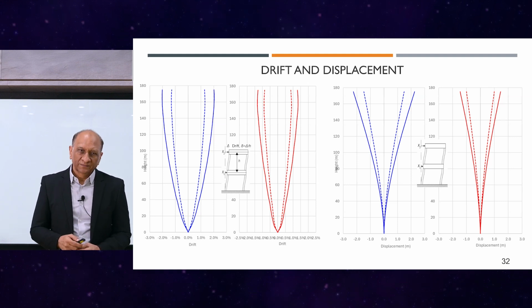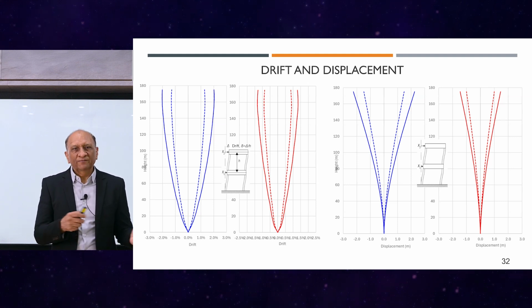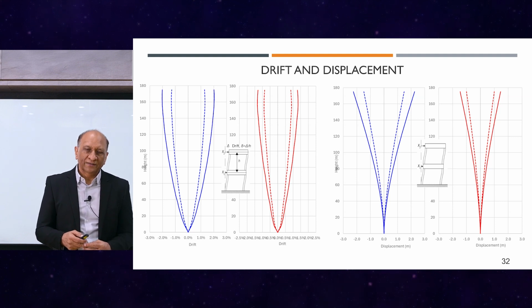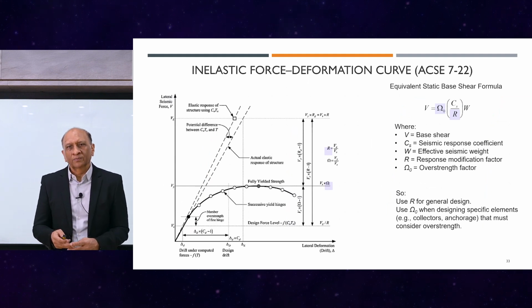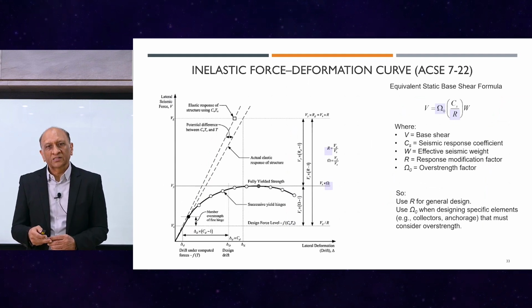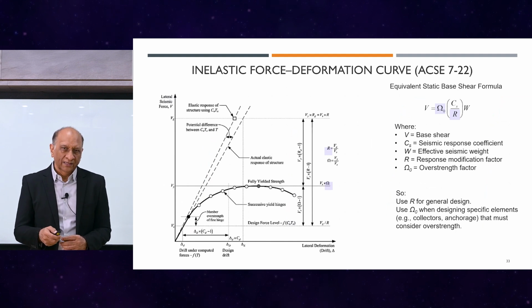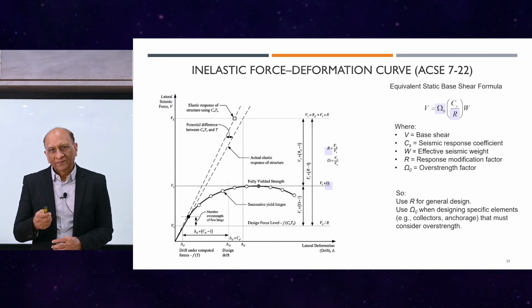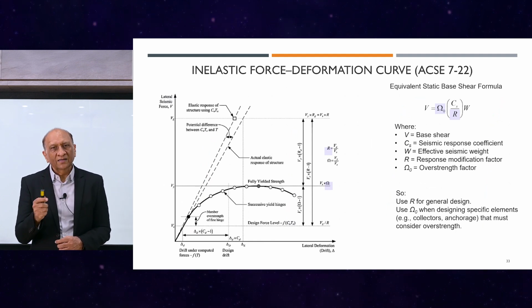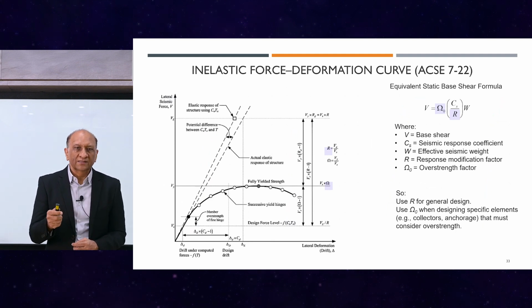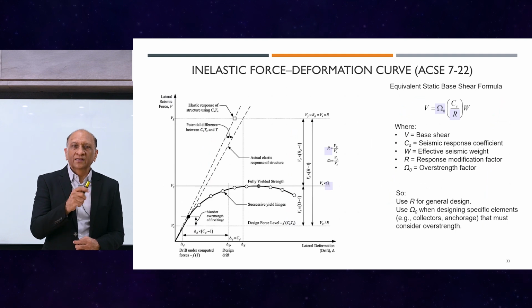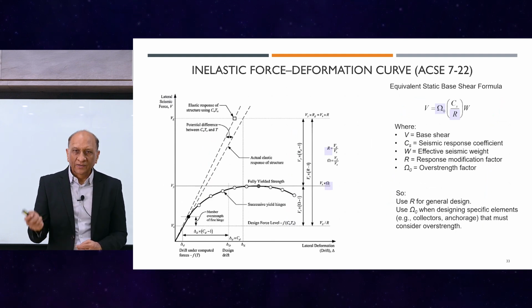Let's move on to another building now, a 10-story building, which is on the other end of the spectrum, and see what happens. For this building, we have maintained the core, although the core may not be as big as this one, but for comparison, we just maintained it and see what happens here. We can see that the natural period is still increasing from uncracked to cracked, not at the same level as this one, but there's an increase from 0.48 to 0.776, similarly as we observed in the 50-story building.